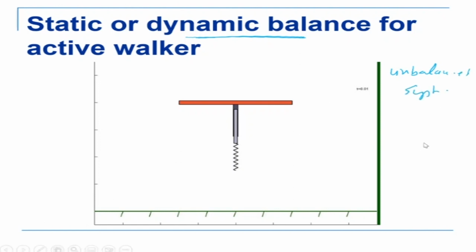Okay, what does it mean? If you look at this, it basically has 1 degree of freedom here, like this, and there is a rotating degree of freedom there. By controlling this degree of freedom, it can jump up and down because there's a spring there. So it can change the position of the body like this, and if it changes the position of the body, the CG is being shifted, right? So it can go this side or this side, depending on that, and it can jump up and down by moving the springs there.